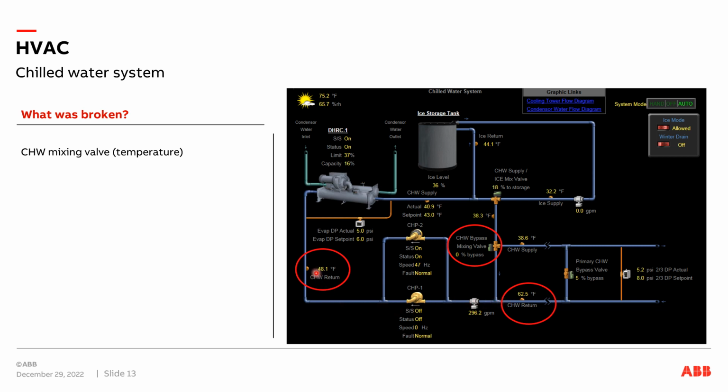And all of a sudden it magically gets down to 48 degrees. Well, how the heck did I go from 62 to 48? The pumps definitely aren't cooling my water down. What was happening is chilled water was leaking through this valve right here because the actuator was getting hung up and not closing the valve all the way. So we were basically not bringing all the chilled water we should have been to the rest of our building, and it was a little bit less efficient.